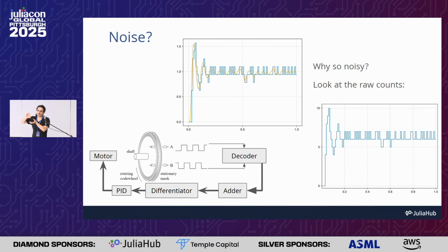Since the encoder wheel can't resolve steps in between them, we're getting like 5, 5, 5, 6, 5, 5, 5, 6, because the true value has a residual that's adding up over time. And that's being shown off by this multi-clock discrete-time model.